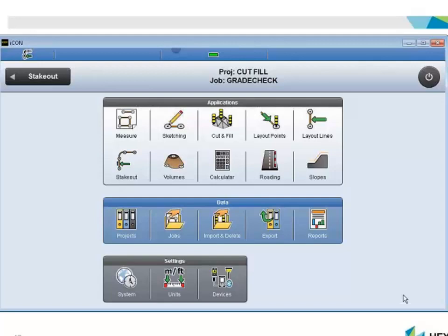So it's possible to extract coordinates from the DXF file, but the point IDs will be generated at that point, so they would not correspond to the point IDs that you saw in the original job. So if the point IDs are important, I suggest combining the DXF with a geo file in Icon Office, or otherwise a TXT or a CSV. And this requirement to export point IDs and point heights as a layer, it is slated for the next release. So come back to the slide now.